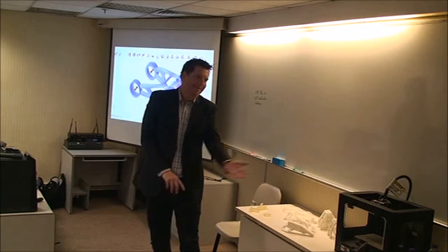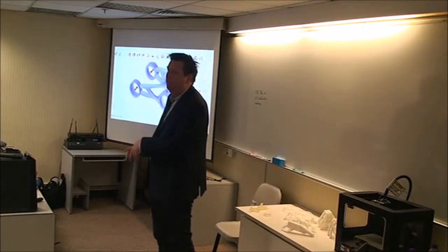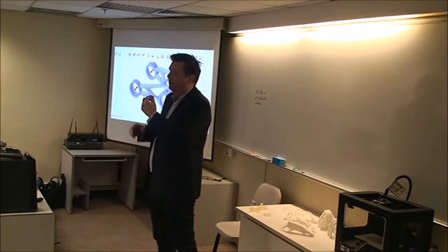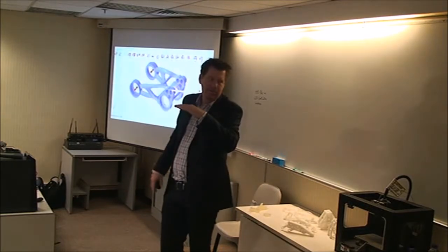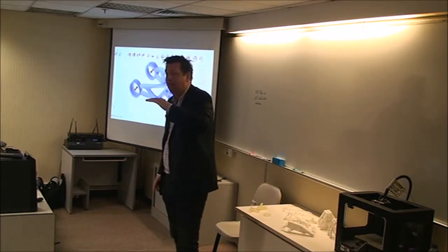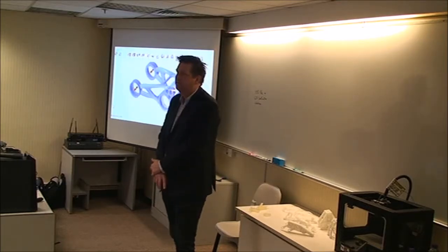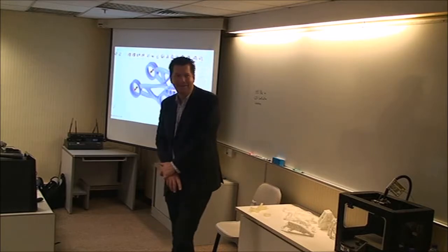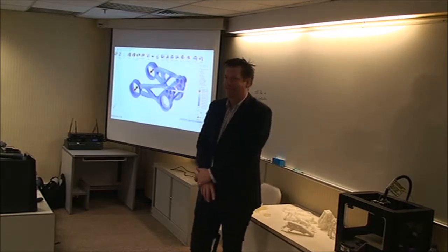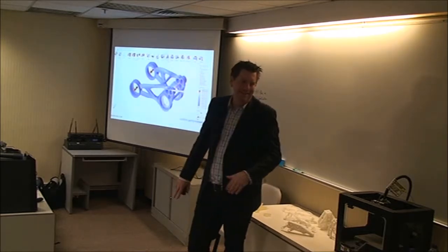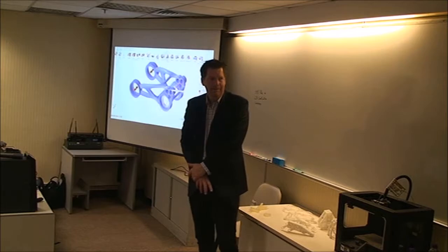Yeah, I think it's. I mean, if it's fatigue analysis, we don't do that in Inspire, but we can do fatigue analysis when you have a load case where, in stress threshold, your ultimate life on the SN curve or something is a constraint. You can set a stress constraint up, so your optimization will keep your stress below that in your load case. So actual wear and tear, that's a dark art in the simulation world anyway. There's not a lot of simulation models that actually model that kind of. So that is very specific what you mentioned to be simulated.